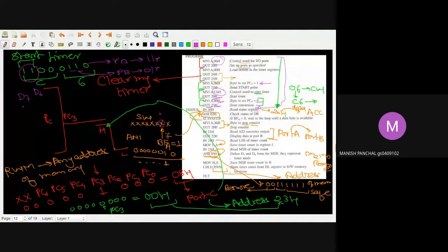तो अगर इस बिट पे 1 आ गया है, मतलब ए टू डी कन्वर्टर ने डाटा पुट कर दिया, तो ये मैंने मास्किंग करी। उसके बाद यहाँ पे चेक किया कि क्या सभी बिट अभी 0 हैं। ये एक्चुअली JNZ का रिवर्स इंस्ट्रक्शन है। तो 2 टाइप के इंस्ट्रक्शन होते हैं, JNZ मतलब जंप ऑन नो जीरो, और दूसरा होता है जंप ऑन जीरो। तो जंप ऑन जीरो ये कह रहा है कि अगर स्टेटस वर्ड के सारे बिट्स अभी 0 हैं, तो आप कंटिन्यूसली इसको मॉनिटर करते रहो, जब तक कि ये बफर फुल आपका 1 नहीं हो जाता।